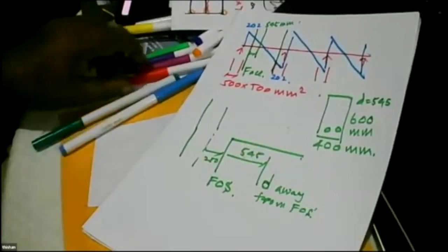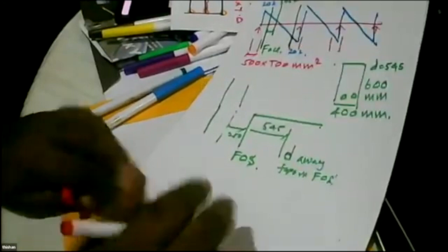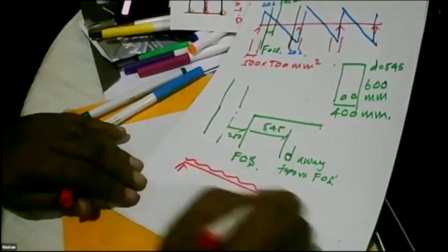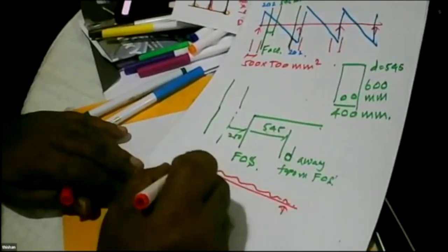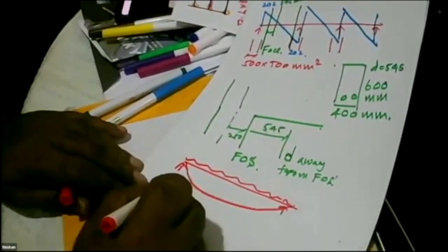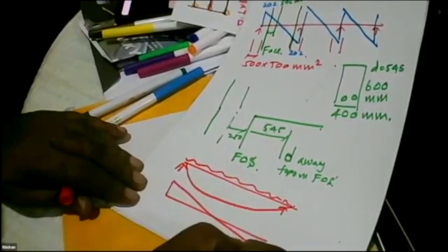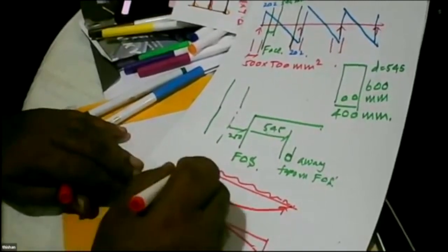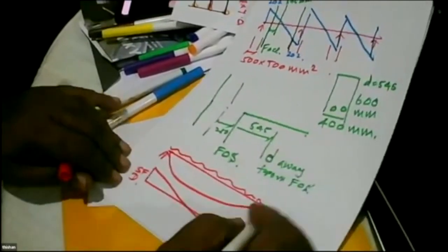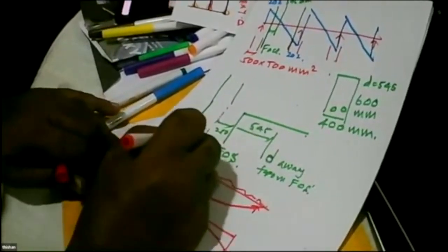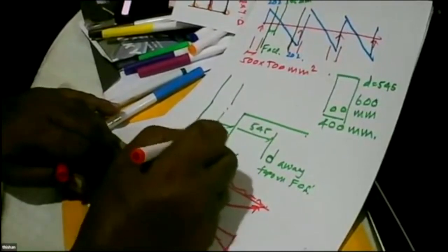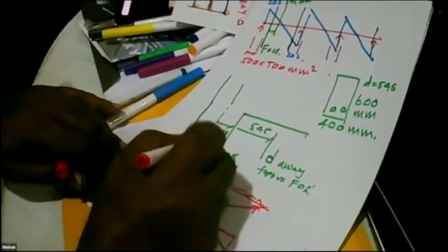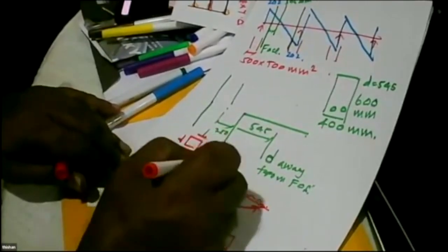The reason is, if you take a section of a simply supported beam, this is the bending moment diagram and this is the shear force diagram. When the bending moment is 0, shear force is maximum. So if you take an element here, what do you get? Only the shear. Complementary shear. Stress, sigma 0.